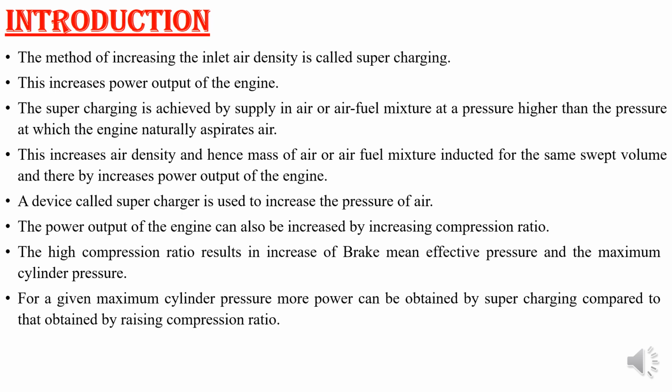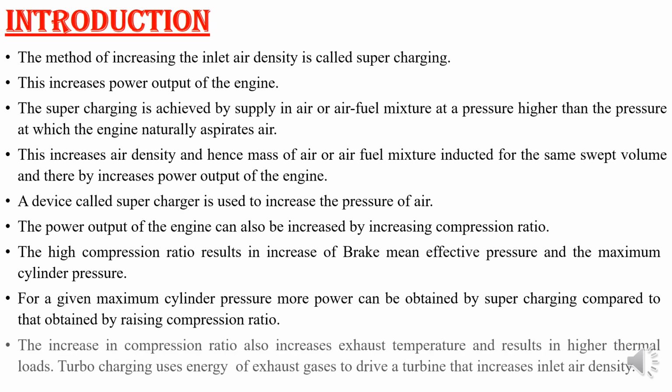So this means that for a given maximum cylinder pressure, more power can be obtained by supercharging compared to the normal case, when we use the same compression ratio. The rate of increase in maximum temperature is also low in supercharging, hence it results in a lower thermal load. So this is how we can achieve supercharging.